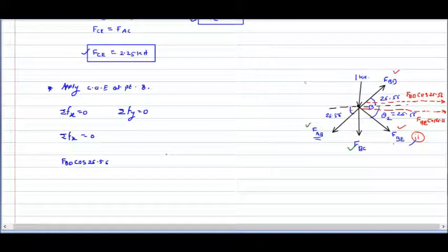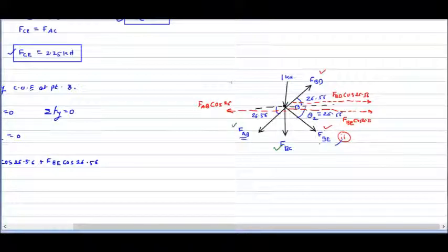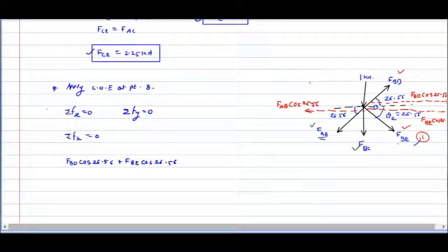Once again, the x component of force in member AB, we also have to use: force in member AB cos of 26.56. This also we can use in our equation, and as per the condition of equilibrium this has to be equal to 0. Now put in all those values we have calculated. Now we have the value of AB only.